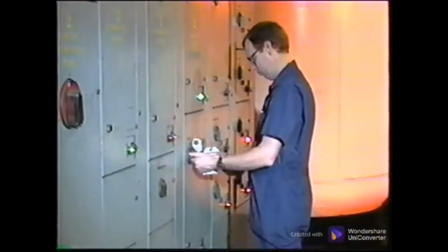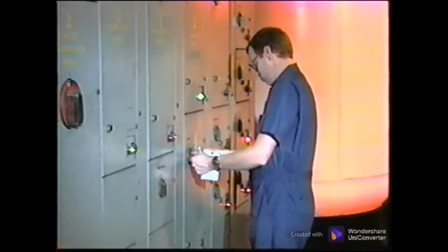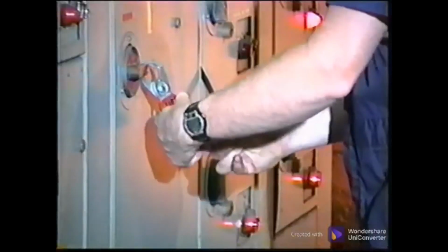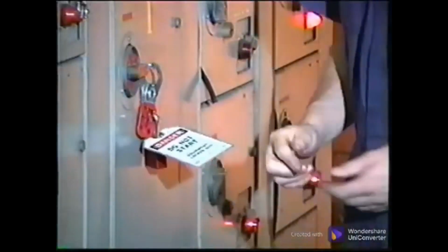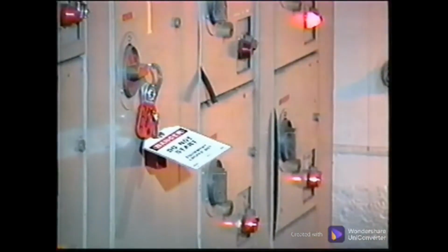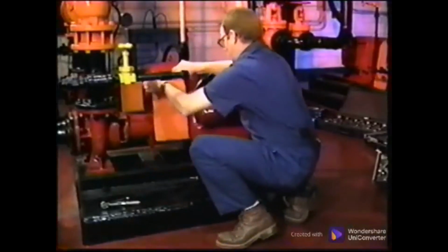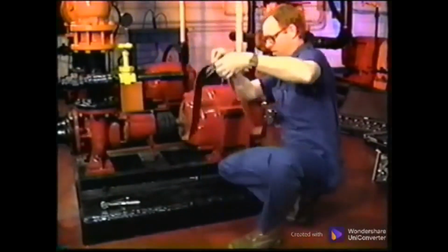After the machine is shut off and locked out, there are 7 checks that must be made before any misalignment measurements can be performed. Some of these may require additional corrective work, but will assure successful alignment. Remove the coupling guard and inspect all accessible rotating parts.